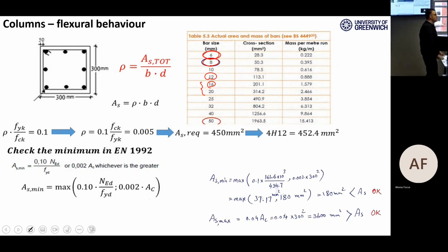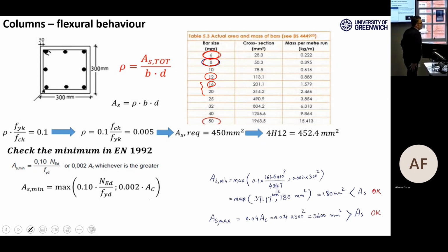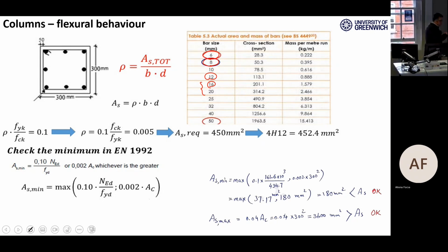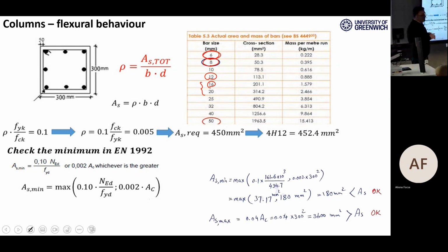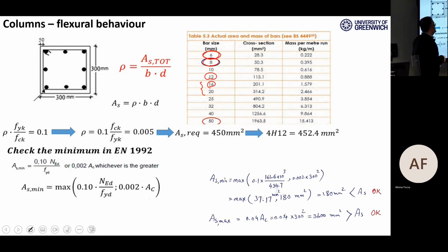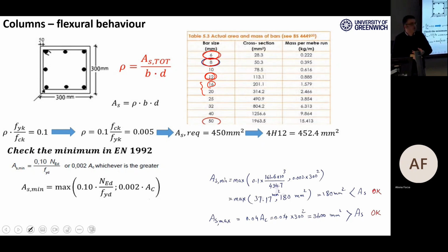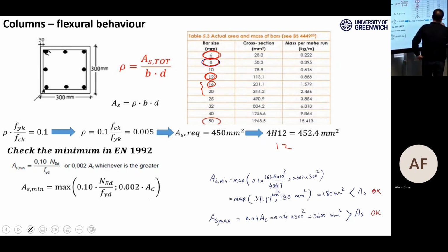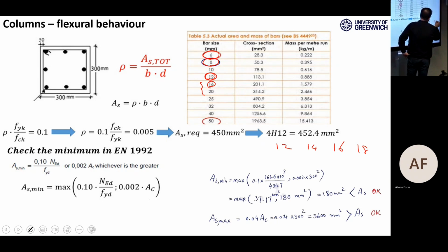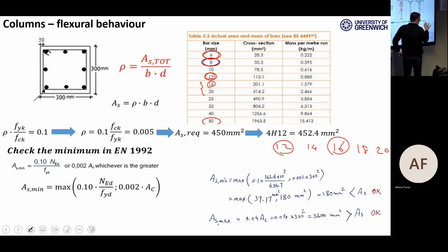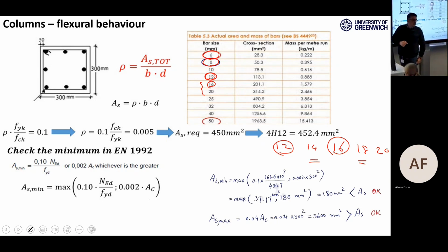Repeat the question, then get it very well. Good afternoon. We usually put one of the numbers in the rebar if you want to choose some rebars to use in our problem. For example, if I have to use number 12, I prefer to use number 16 for other elements, not 14. Like this, 12, 14, 16, 18, 20. I prefer to use this and this, or this and this, so that it is easier to differentiate for workers because they would see it.